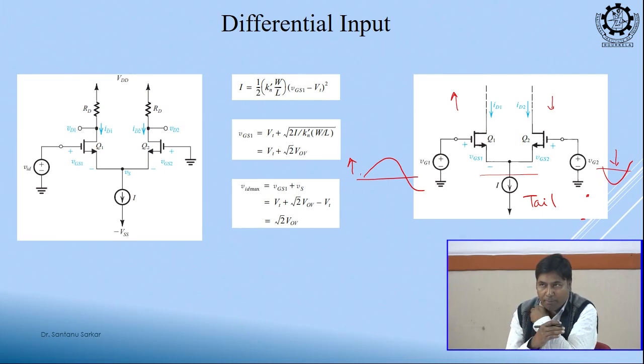Okay. So on top of the DC, as we discussed in the single stage amplifier, on the DC bias we will superimpose AC. Same concept, but while doing the small signal analysis, all the DC sources are removed, right. So this is grounded, but you can think that this is not actually ground.